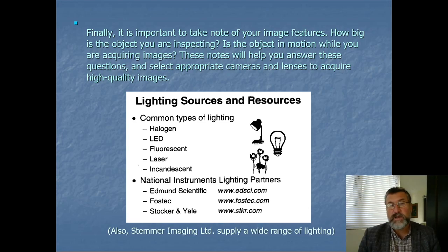There is one advantage a halogen might have over an LED, which is that a halogen light, or a conventional bulb, produces a continuous spectrum. Because the filament, a tungsten filament, is actually a black body emitting radiation at a temperature of 5,000 Kelvin. So it's got a continuous spectrum of wavelengths. If you want a particular wavelength, you can always get it from a halogen light by means of filtering or just selecting certain wavelengths. Whereas LEDs have specific wavelengths, more discrete bands rather than continuous ones. So that can sometimes cause a problem. Sometimes you do need a continuous spectrum.